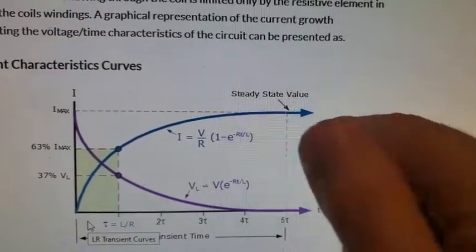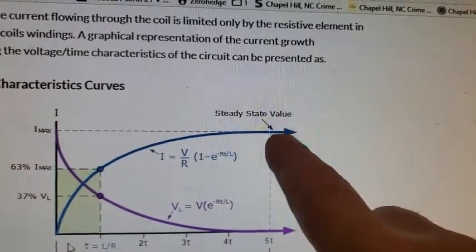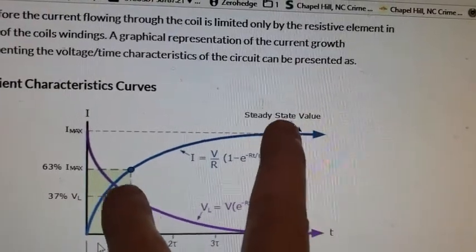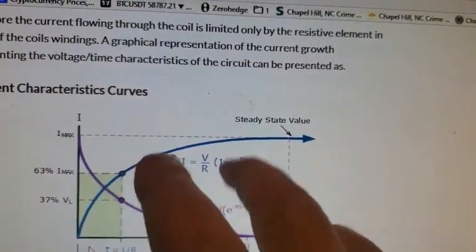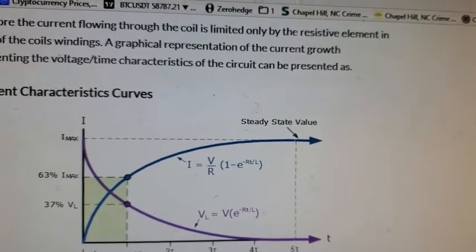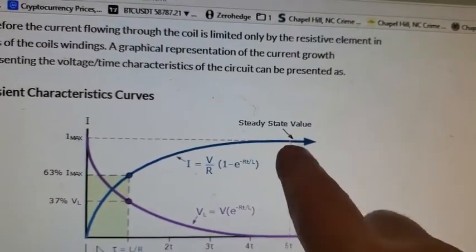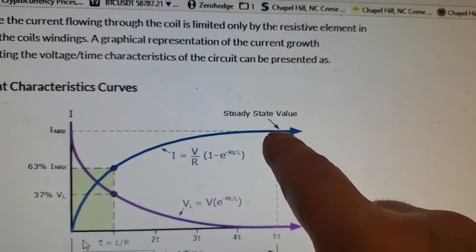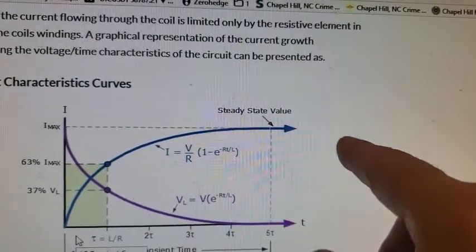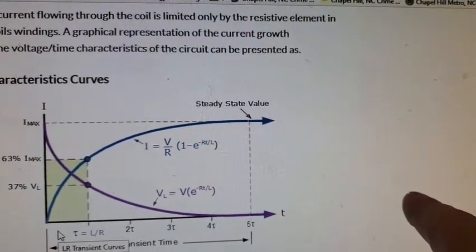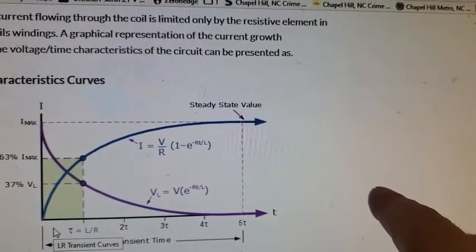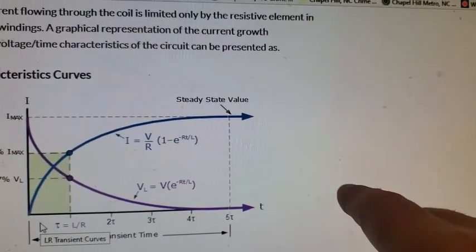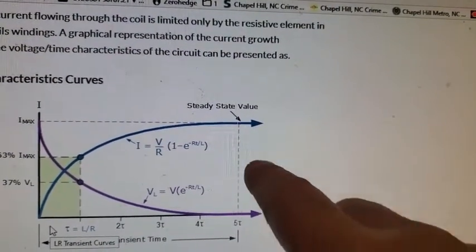So if you were looking to grab the inductive spike, if you charged a coil up, there would be one inductive spike you could grab there. It would be difficult to do without a short. Grabbing this charging up is what's done in what's called a boost circuit, a boost DC-DC converter. And then the coil will collapse when you shut the power off. If you grab that inductive spike, that's a setup with a diode termed a buck boost DC-DC converter.